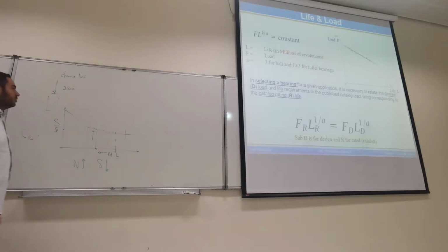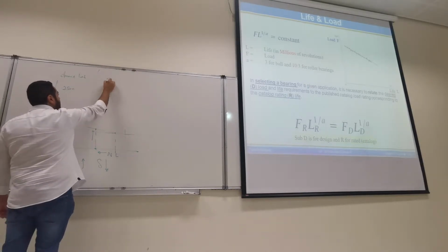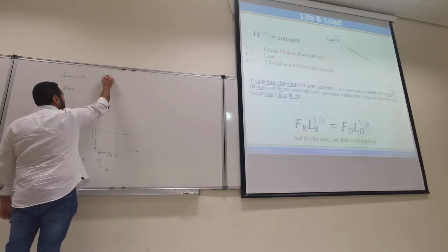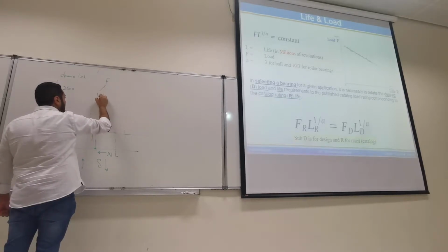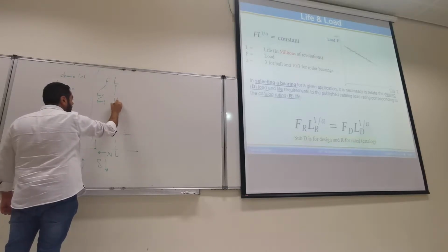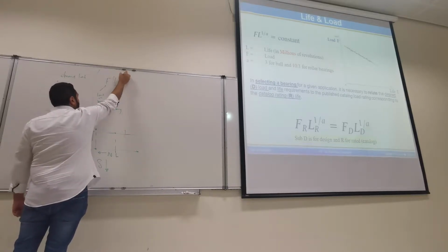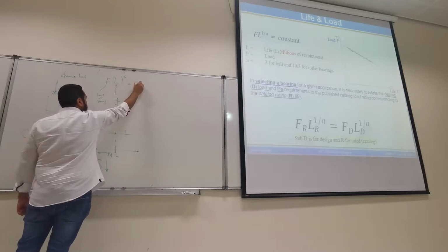Right. So same thing in the bearing. The relationship is governed like this. The load, so this is the load on the bearing, times L, life of the bearing, power 1 over a, is equal to constant.